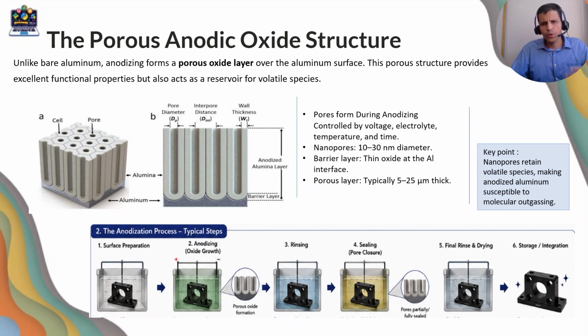But sealing is also used to add color. In this example, you can see the black anodized optic mounts, which go through the surface preparation and the sealing. So the organic dye, like the black dye, is added. Not only black, whatever color is needed can be added based on the dye. Mostly in optics mounts or assemblies, black color is used for optical performance. Once the sealing is done, the pore is completely filled with the dye. Then it will go to the drying stage and then to packaging.